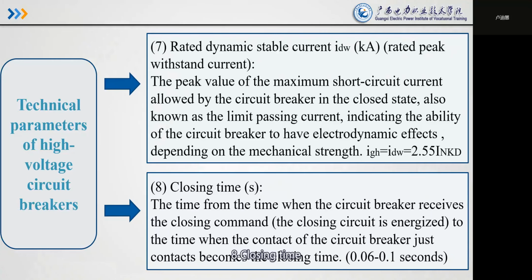8. Closing time. The time from when the circuit breaker receives the closing command, the closing circuit is energized, to the time when the contacts of the circuit breaker just touch, becomes the closing time.